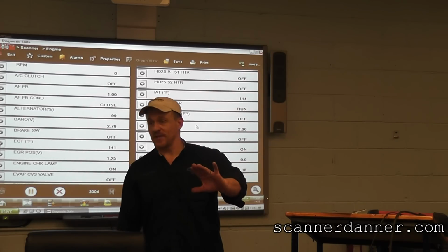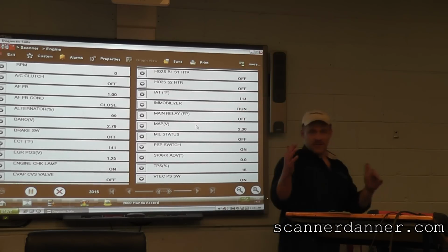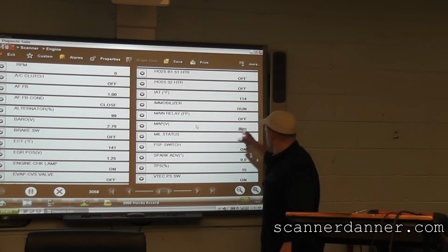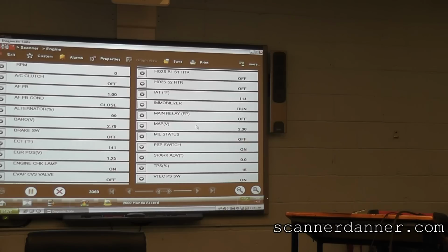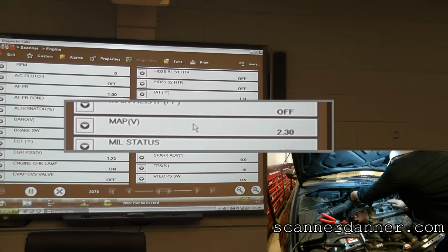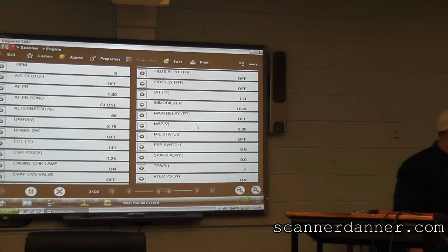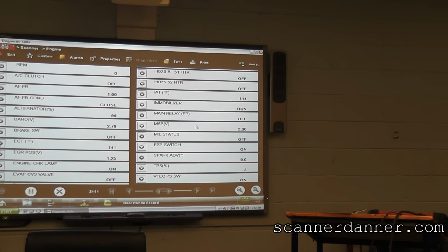There's a 3-wire pressure sensor that's sitting on top of the intake manifold. That's my MAP sensor. There's no hose on this one, so it's directly mounted. There's a hole drilled in the manifold, okay? I'm just watching my MAP data PID right here. Watch this guy right here. I'm going to unplug it and make a determination of something, possibly. Okay, no change whatsoever. And the next thing I'm going to do is I need to crank it to get an RPM signal. I'll explain why in a minute. Still no change on the MAP. Did not expect that.